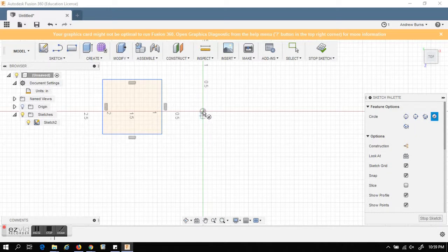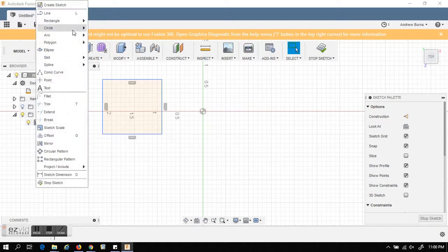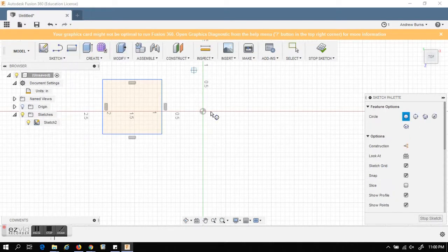The center point circle is very easy, very simple. Basically, you set from the center the diameter of the circle. Pretty simple, especially if you're doing anything like making a hole. That's very helpful. Then you've got a 2-point circle, which instead of defining the circle from the center point, you define it by the 2 endpoints, or the points straight across from each other. So that might help with positioning the circle.